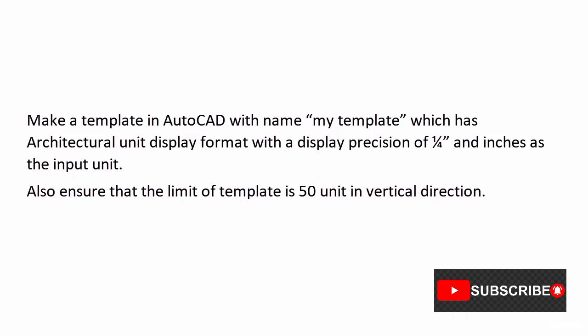So now we have completed the first module. Let's look at our first question, which is related to the topics which we have covered in this module. So we need to make a template in Autocad with name my template, and that template should have architectural unit display format. Also that format should be at a precision of 1/4 of an inch. Also ensure that inches is selected as the unit, and the limit of this template should be set at 50 units in vertical direction. So these are different points that you need to keep in mind.